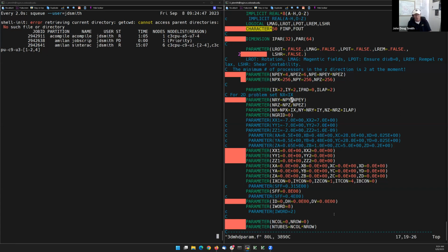Right, and you'll go through and these things will already be set. You'll be able to change your processors, but we will set the grid size. We will tell you in this file, you can change this, you can't change that, so that you'll know which parts are actually a part of the simulation that we want you to run and which parts are open for you to change. The things that we will typically begin to change, and this is where, to answer your question a little bit more, Jeanette, these flags up here control what factors in the simulation may make it more complex, right? Rotational, magnetic field, things like that. We may turn those on and off. We may change the grid size and set some constants in such a way that the model gets way more complex.